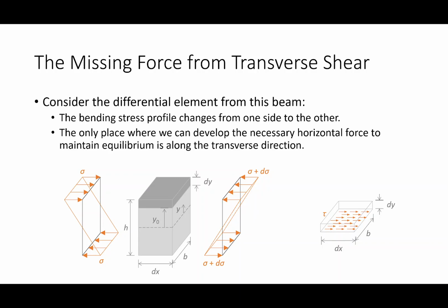So we have a beam, you know, this line right here, that's the neutral axis, right? So if you take a beam and you bend it, and let's say it looks like a big old smiley face, the top of the beam's in compression, the bottom of the beam's in tension, and that line in the middle doesn't really deform at all. We call that the neutral axis. Like it changes shape, but it doesn't get longer or shorter. And that's this sort of line through the middle right here. Everything above that line is in compression, everything below that line is in tension, okay?